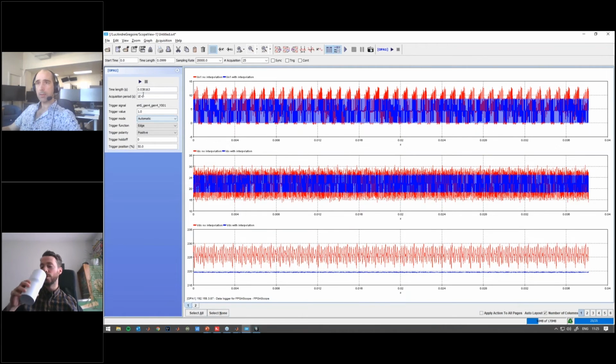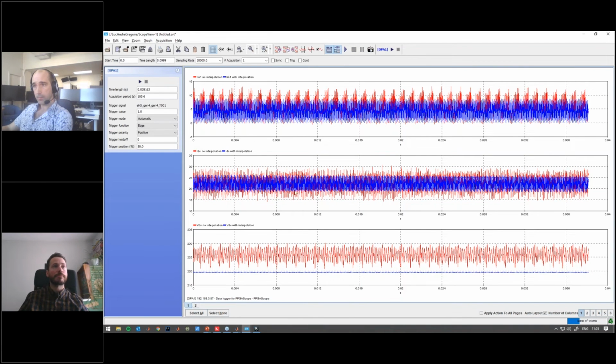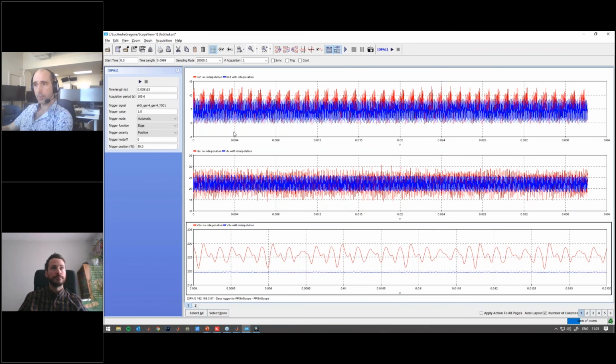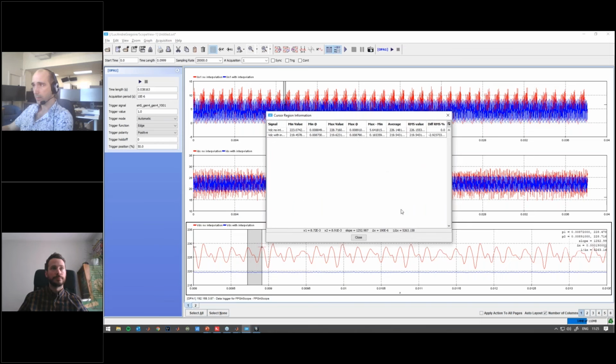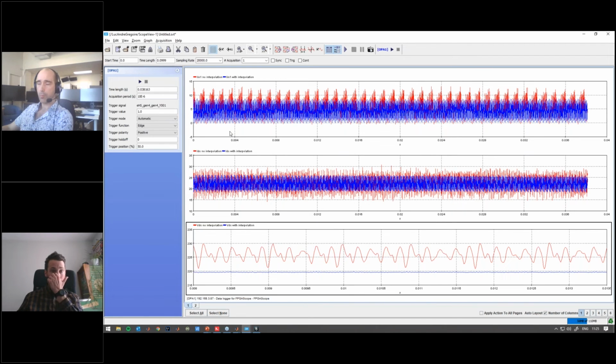Yeah, so let's say that we put one sample here. To explain aliasing, let's say that we do the sampling every 10 microseconds. Let's just look at the red signal. You can see that this signal is like this. If we look at the frequency between two harmonics, it would be around 5 kilohertz. And aliasing basically means that you don't have enough samples to properly represent the signal.